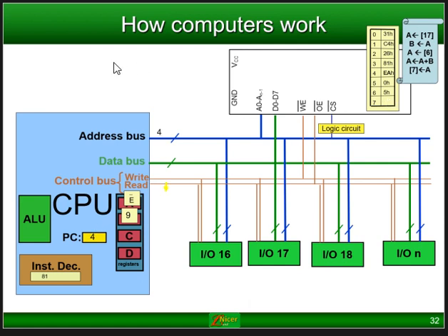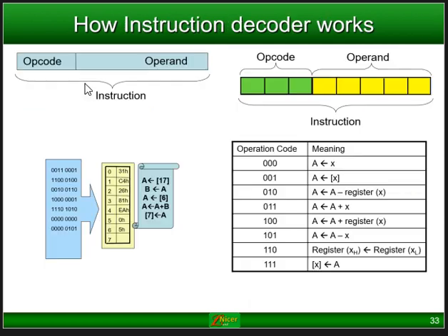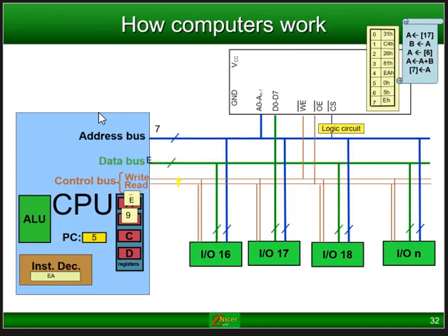So let's get the instruction. Number 4, there it is. It's been placed in here. And if I now carry on again, it will place the address. Remember, it must take the value to address number 7. There it's placing it here. And now it's taking the data, placing it on the data bus, and let me just go back. There it is. It's stored, that value. It was stored in position or register number 7 there.